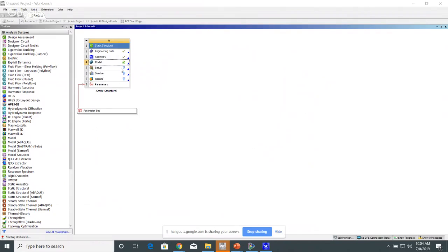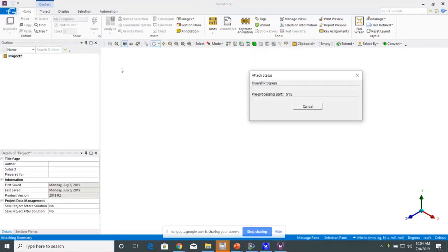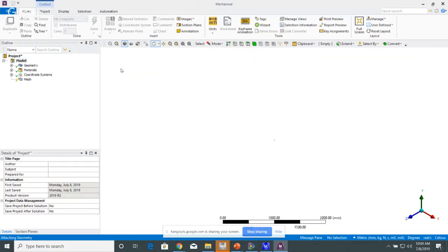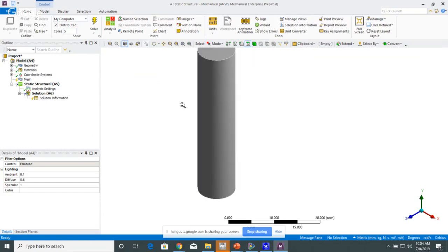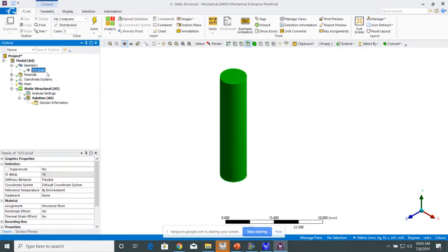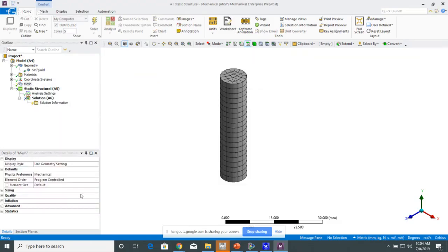I have some videos on Creo and NX linking with ANSYS on our YouTube channel. So that shows you an example of how you'd connect a standard CAD tool to ANSYS to do the same thing. If you're using a standard CAD tool, the parameters will come in under each part, and you'll see an option down here that allows you to specify the parameter. We can mesh it. Anywhere where you see this box, if I click on this, this becomes a parameter. Click on it again, it's no longer a parameter.